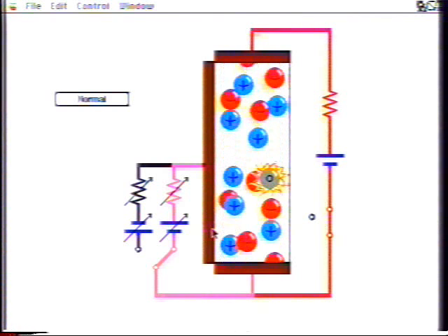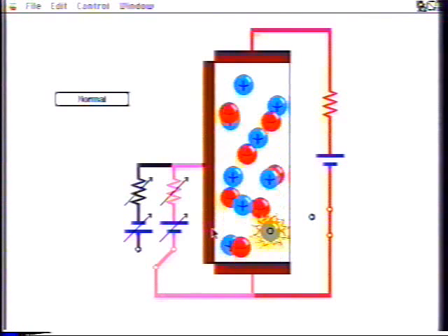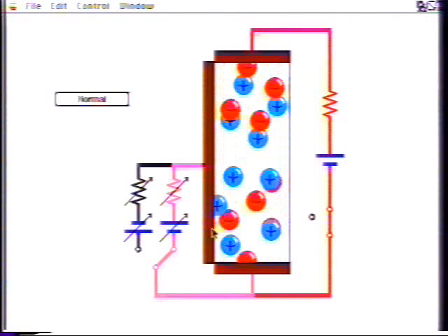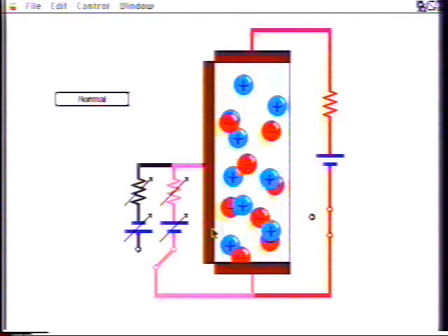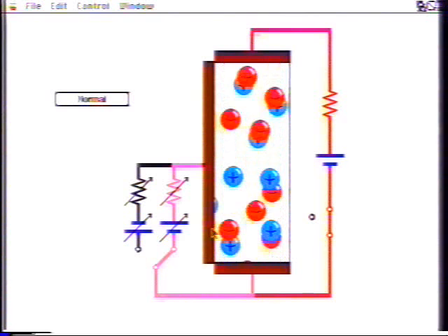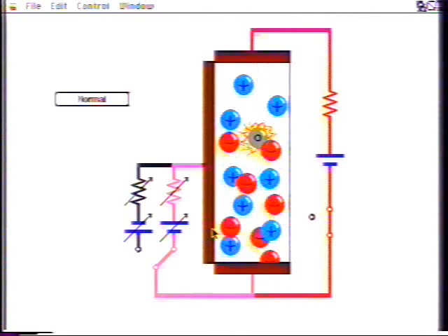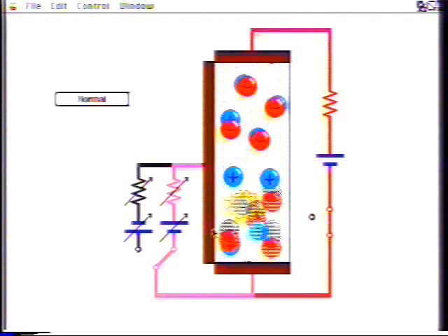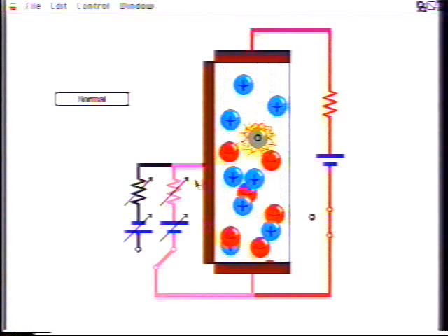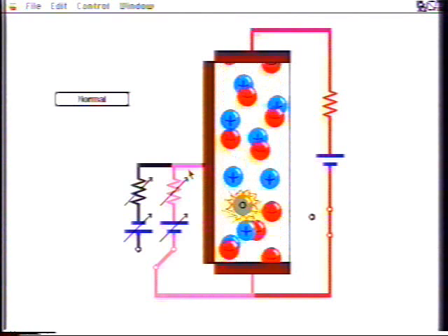From a device point of view, the steady-state base current is a second-order effect and is undesired. Great effort is made by device designers to minimize recombination in order to keep the DC base current as small as possible, indicated by a pink color in this animation.